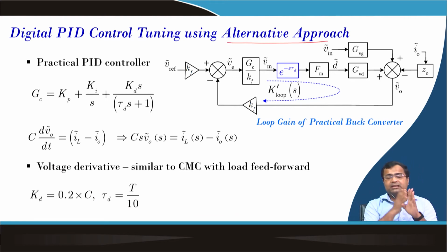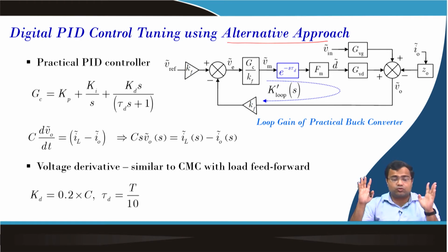So, this was the earlier stable pole zero cancellation, which is highly sensitive to resistance and all, and we will see that when you go for output impedance shaping, this method may not be the right way, because we are talking about the closed loop output impedance.